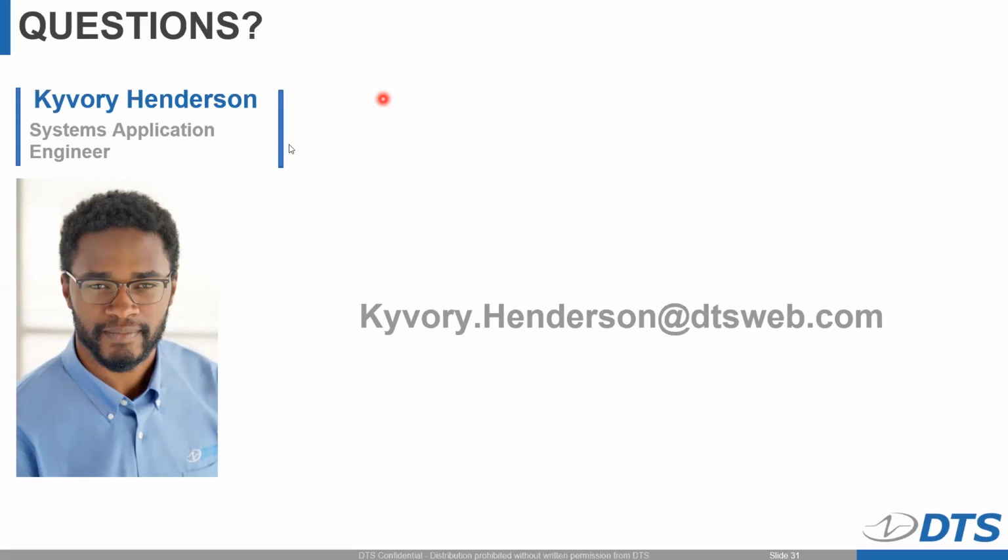Okay, I have another question here. Can you display FFT in the software? Software is pretty simple and basic with data viewing after the test. So you would need to export that data in order to run any kind of FFT. Okay, additional question. Are there calibration requirements? So the DDR is calibrated by DTS versus NIST reference standards. And recalibration is also available here at DTS. And most of our customers will recalibrate once per year.